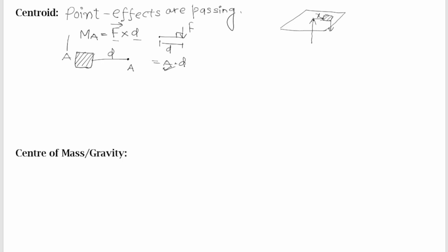So, if you place your finger right below this point, I take an area. It is a possibility that an area of the same magnitude placed at the same distance x will counter this. So this system is trying to tip the paper in the clockwise direction, but the same area placed at the same distance on the opposite side is trying to counterbalance it. It's not necessarily that the same area at the same distance is counterbalancing. There might be a possibility that a larger area placed at a smaller distance also counterbalances, but no one can actually tell you what is counterbalancing which section.